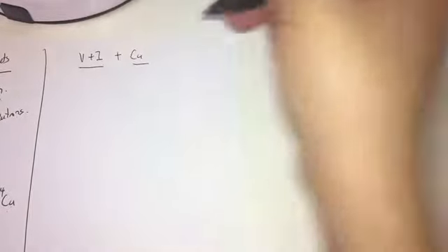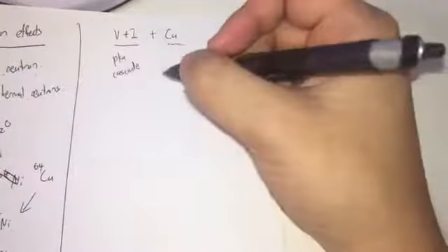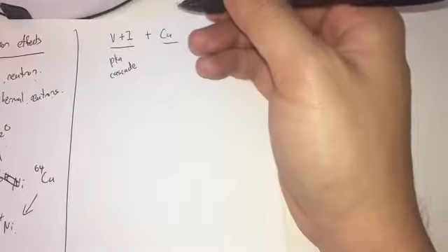However, this copper can react with the Frenkel pair, these vacancies and interstitials generated by the PKA cascade, or the depletion zone. There are some things that can happen in an alloy, and we want to discuss how this happens now. We have discussed transmutation. Now we want to discuss how this copper interacts with the vacancies and interstitials caused by irradiation damage.